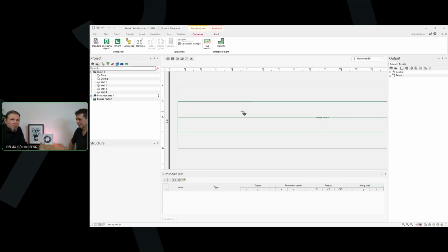In the old one, there was a limit to 2 meters, as Klaus told us. This is absolutely right. So it means if you have 4 meters, you need to have two escape routes through, that's the way it was written in the past. And this has now changed, because now the surface will be evaluated. If you have a width of, for example, 3 meters in total, then you can reduce at the side from 2 meters, half on each side, to 1 meter.